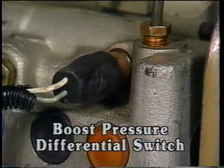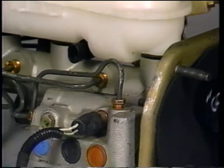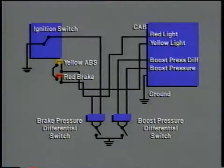There's a boost pressure differential switch mounted on the pressure modulator. It has a single terminal, is self-grounding, and is normally open. This switch performs the same function as a differential pressure switch in a conventional brake system. If a leak anywhere in the brake system allows loss of pressure, the difference in pressure between the primary and secondary sides of the hydraulics pushes the switch to one side and grounds it. This signals the controller that something is amiss.